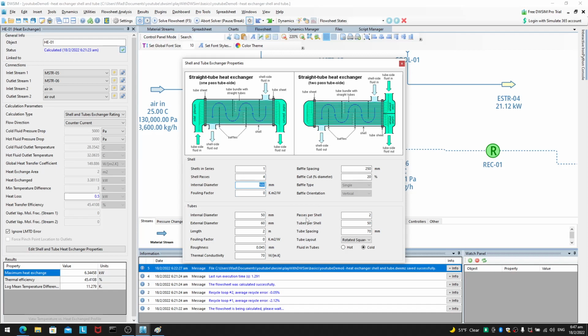So let's just set some rules of thumb straight, important reminders. Internal diameter must be less than external diameter, obviously, or else it's just not physical, right? And external diameter must always be less than the tube spacing, or else the tubes will be touching each other, or even worse, crossing each other, which again doesn't make sense. So these three must go in order, because that's the way things are in reality, right?